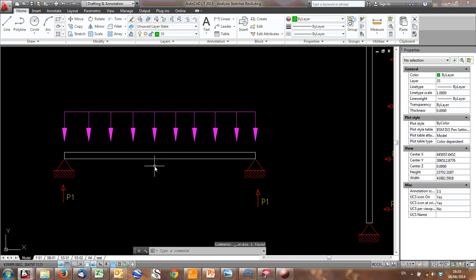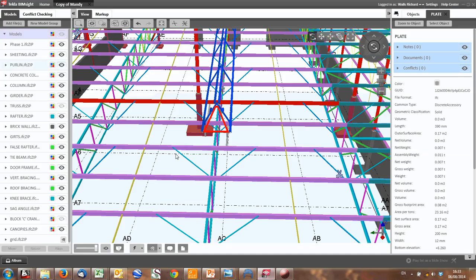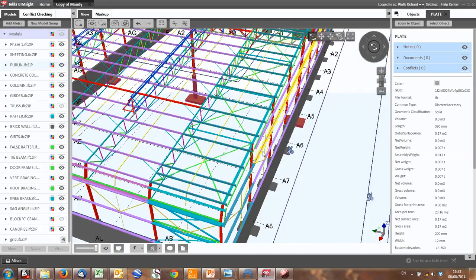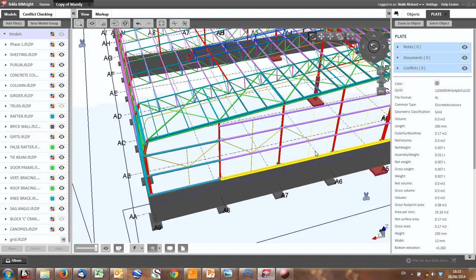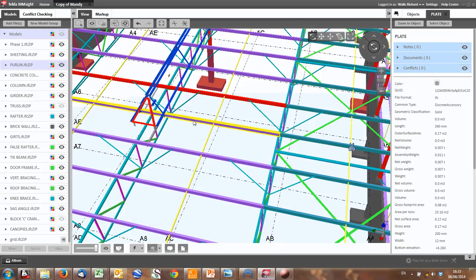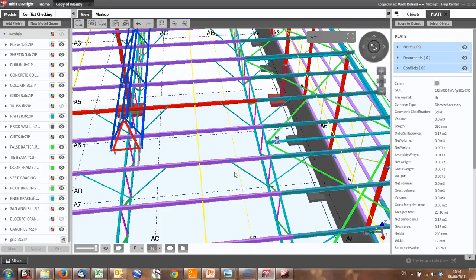Normally, you can often just design them as simply supported, but you may need to check for multiple spans depending on what's stipulated, or you can just state that purlins come in single pieces, but often the contractors like to erect these covering multiple bays. It really depends on how they're erecting it, especially the girts. You can put one girt covering 2 bays. It just makes the work quicker. Right, so we can analyze this though as a simply supported beam spanning from truss to truss.